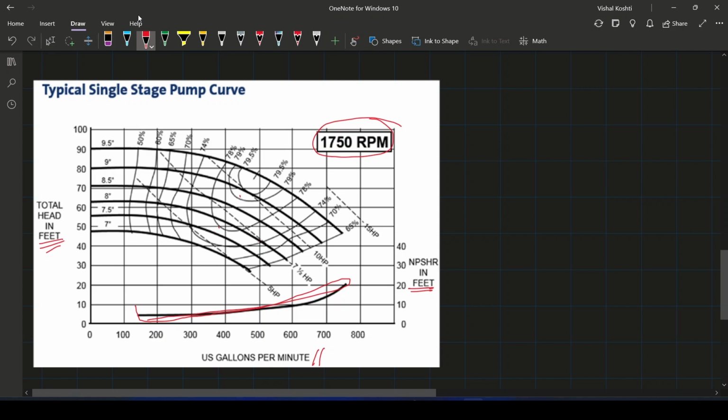And here, when we look into it, the dark line is the discharge versus head curve. And here you can see these kinds of curves. That is the efficiency. Here you can see that at this point to this point, the efficiency is the same, that is around 79.5%. And when we go to this point, over here and here, the efficiency we get is 79. As we go further, the efficiency decreases. See here at the extreme ends, we have low efficiency.